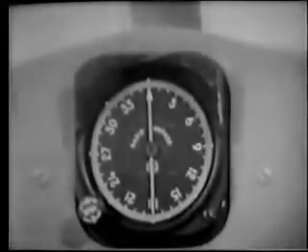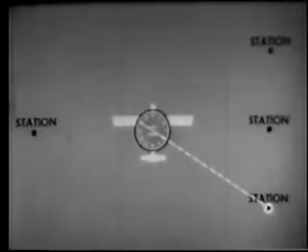After the receiver has been tuned, the indicator is used for locating the station. We visualize this as a scale surrounding the aircraft. We know that when we tune to a station off to the right, the needle points off to the right. If we tune to a station to our left, the needle points to the left. It always points toward the station to which the receiver is tuned. It tells you where the station is located relative to the aircraft.